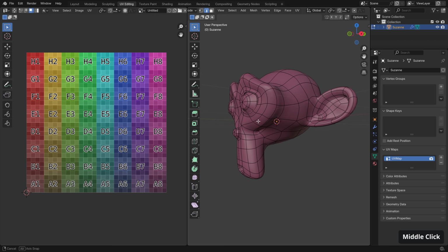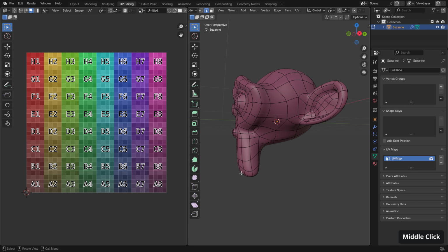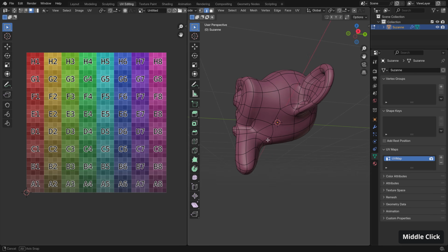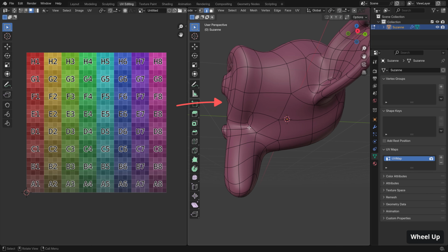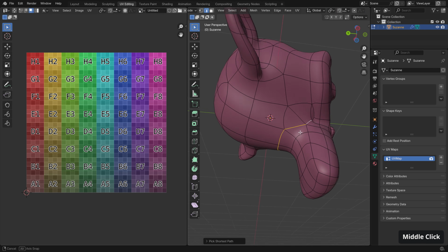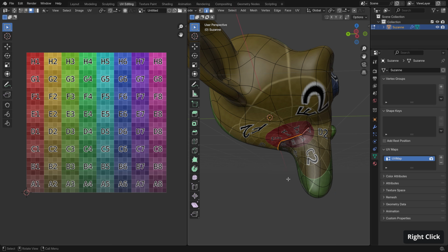First off, let's separate out the different shapes. Now we have this mouth area here, which is basically a cylindrical shape. So I'm going to cut that away from the head, which is more of a spherical shape. Now, also going to keep in mind that we have this flat area, which is the face, so we don't want to cut into the face. So we just want to cut around the mouth here, behind it, to separate the mouth from the head. So we're adding our first seam over here. Look at the seam, so now we separate the mouth from the head.